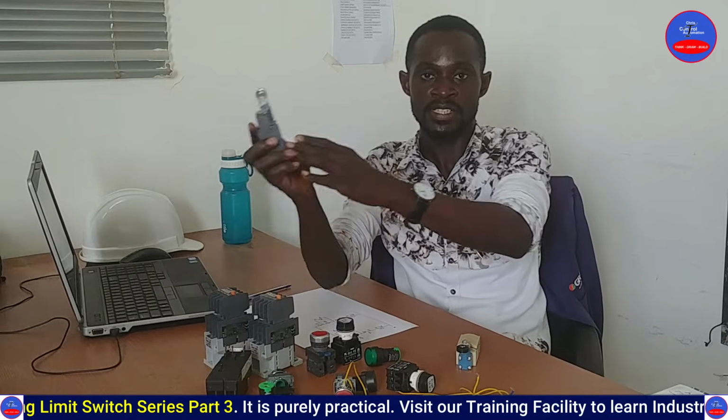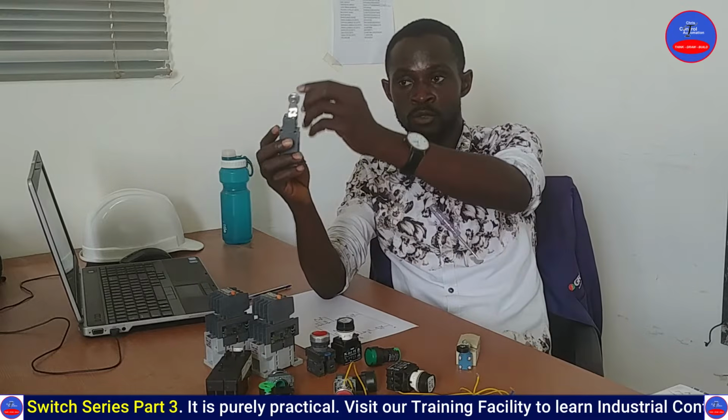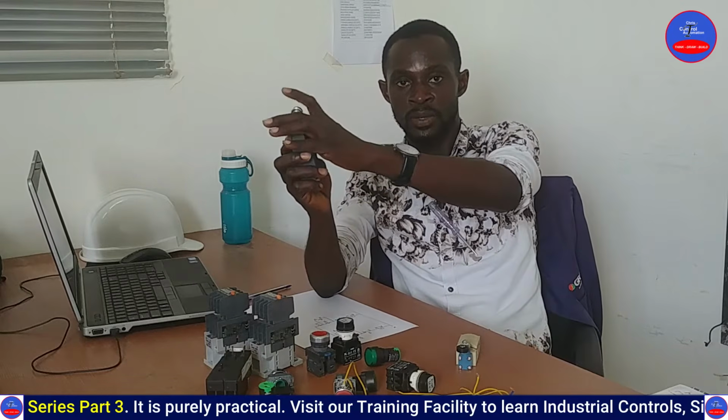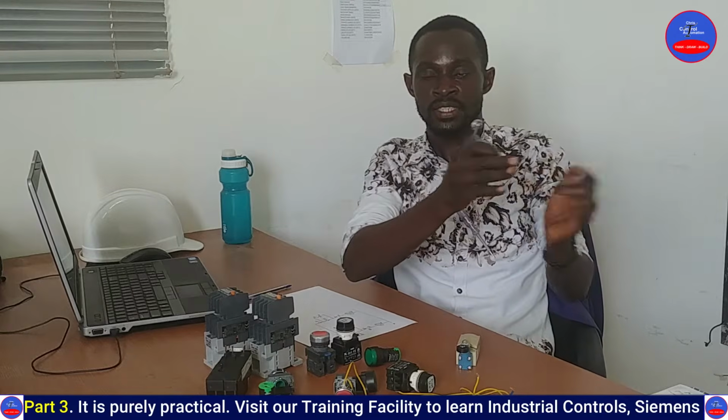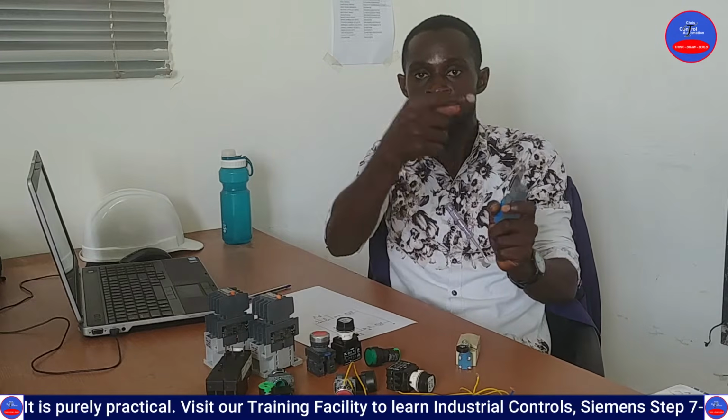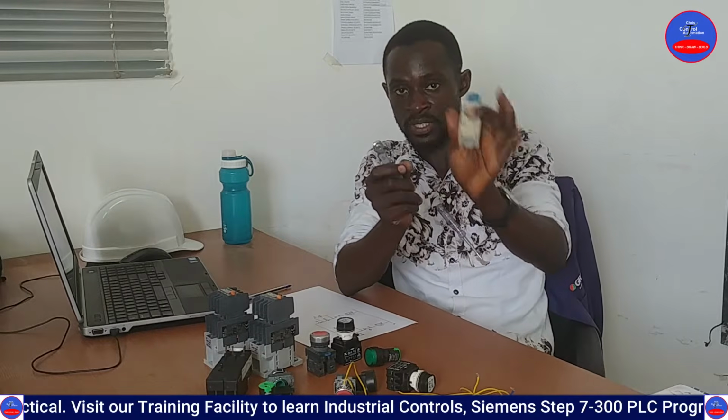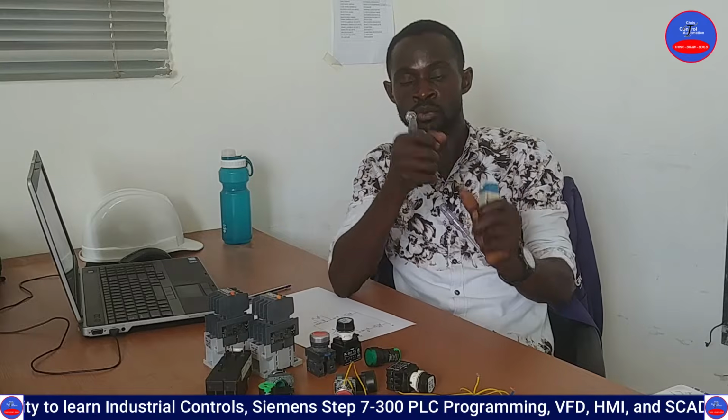When it gets there, it will hit the limit switch 2, and then it will reverse its direction and return to the initial position where it started. When it gets to where the limit switch 1 is, it will hit it and then it will stop. But it is not going to move in the forward direction again